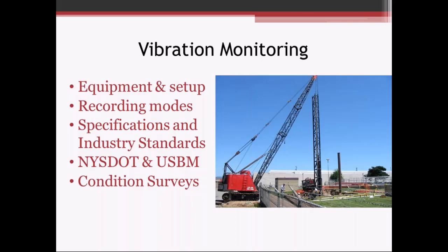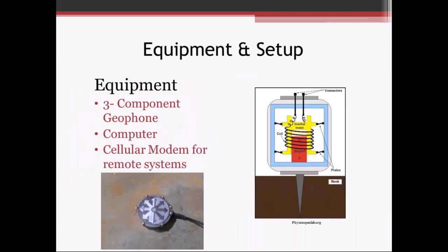So we'll get into the vibration monitoring. We'll talk about some of the different equipment that's used, some of the different types of setups, recording modes. We'll talk about some of the pros and cons of different recording modes. I'll show a handful of different data that we've collected over the years. Again, we'll talk about some of the specifications, industry standards, specifically New York State DOT and the U.S. Bureau of Mines RI 8507 standard, and then we'll discuss some condition surveys a little bit also.